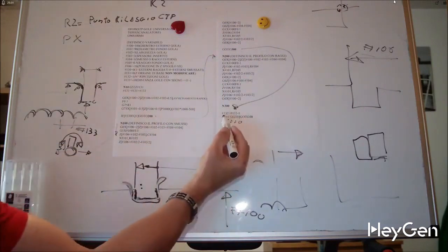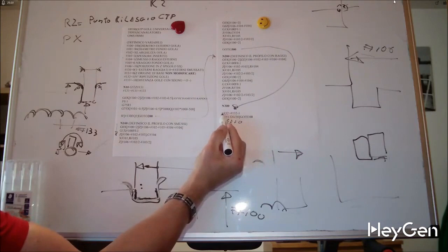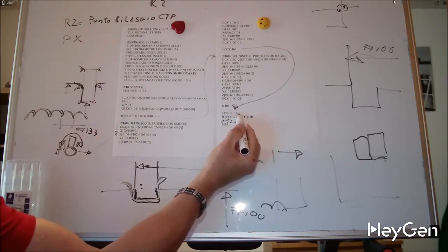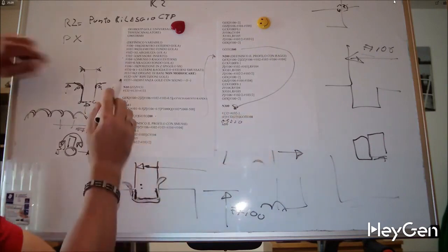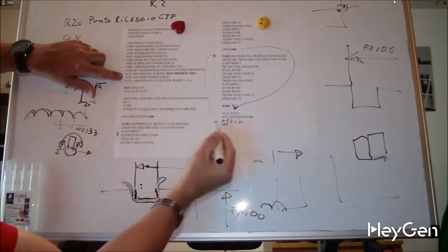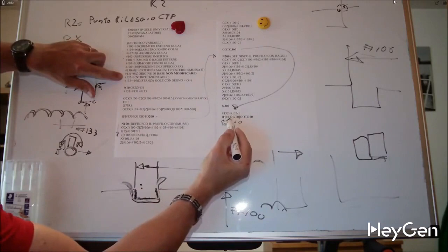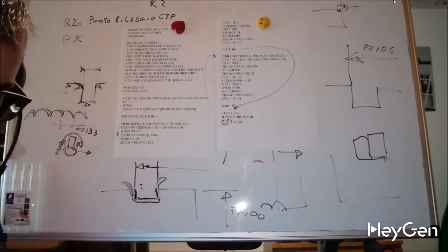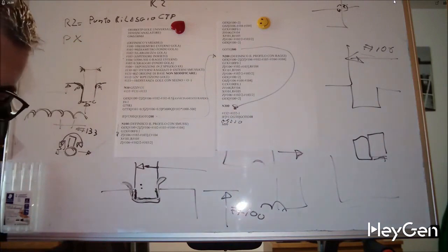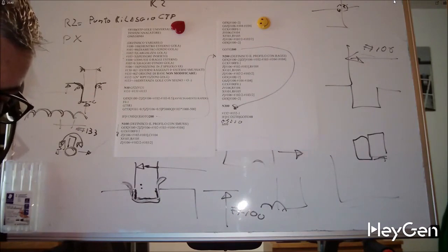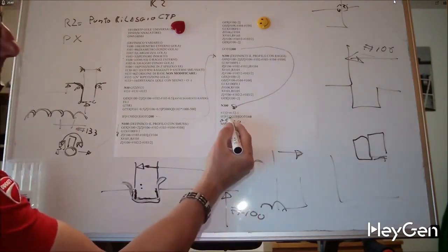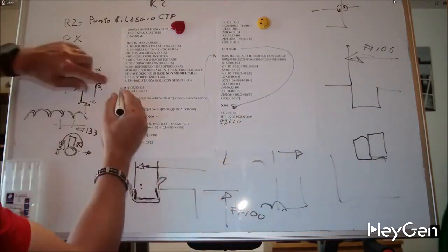When I get to N300, what do I do? I take #132 and subtract 1 from it. So #132 is indeed my repetitions. If #132 is greater than 0, I go back to block 10 and execute it with #131.